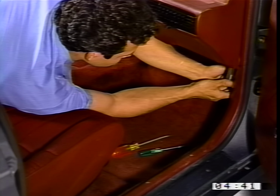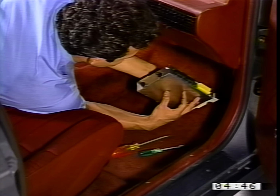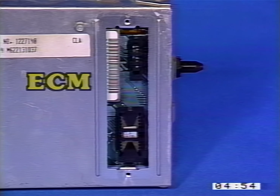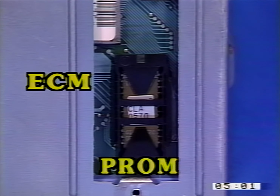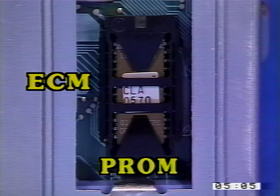The ECM, the heart of the GM C3 system, can usually be found in the passenger compartment. For exact locations, consult a component locator guide. The ECM has two parts: the ECM itself, which is replaceable, and the programmable read-only memory chip called a PROM. The PROM tailors the ECM to an exact application.